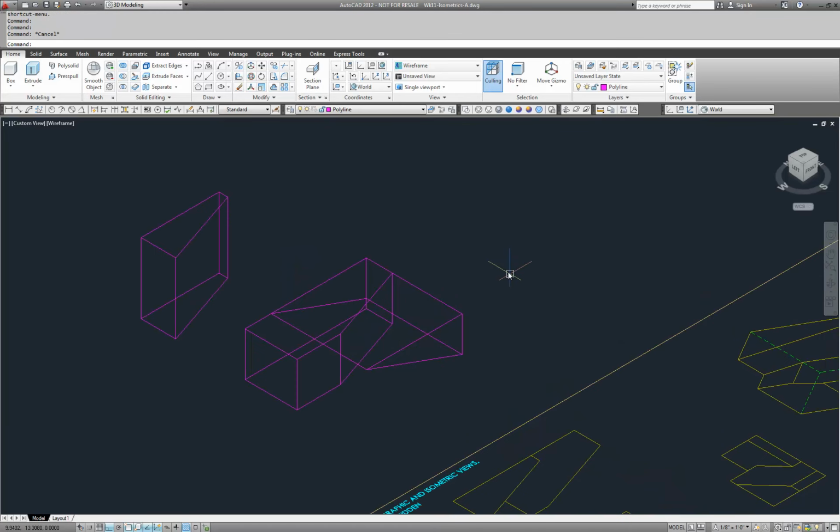So I'm going to go up here, and here we have a new tool that you're going to get to use. Right in Solid Editing, on the left-hand side, you have Union, which, if you think about it, puts two things together. Subtract, and intersect. We won't be using intersect, but we're going to use subtract today, okay? And union. So subtract, you pick the object you want to subtract from, enter, then reach over and grab the object you want to subtract, and then enter, and look at that. It just took it right away.